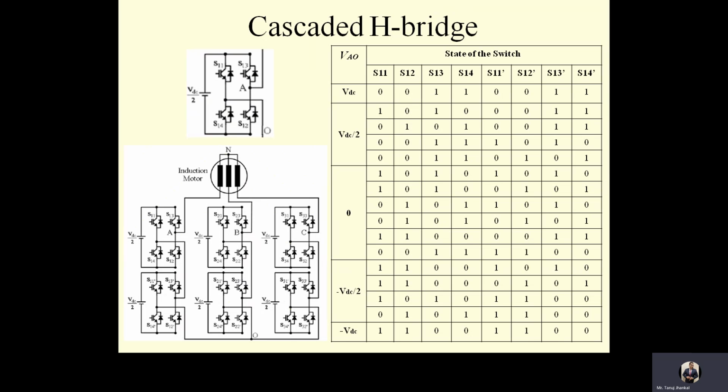A scheme of modular multi-level inverter is investigated for a medium voltage induction motor drive where two three-phase inverters feed the same motor through two different groups of coils of the machine, where the switching state redundancy can be best utilized for equal distribution of switching losses among the various cells.